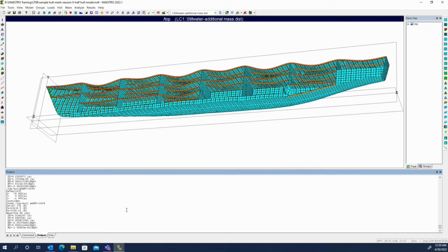If there's a specific set of nodes or plate areas that you're interested in, and we've done this in the past, I think I had mentioned when we did that dry docking model, they had a set of optical sites along the wall of the floating dry dock, and there were like 6 sites down along the length that they would monitor each day to make sure that the dry dock was remaining flat. When we did our model, we created a nodal group and we recorded those specific locations along the hull and we made a nodal group.